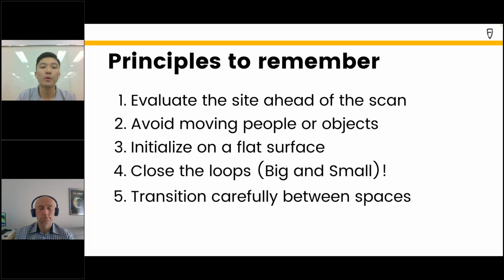Here are some key principles to remember for any 3D scanning project. First, you need to make sure you plan ahead, and you will thank yourself later before you do the scanning. A simple walk through the project area before you begin the scan can help you identify areas that might create some challenges to the scanning mission and save you a lot of time and rework.